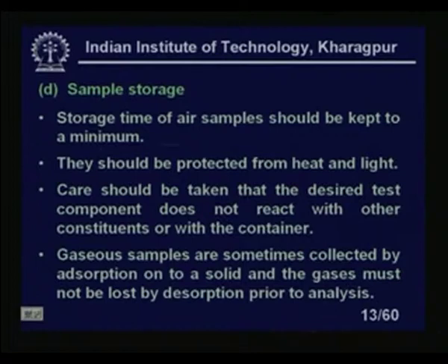Many samples are collected by adsorption, that means the gas will be on the solid material and it should not be released, or desorbed, prior to the analysis. Okay. Because if it is released before the analysis, obviously that particular gas will be lost, we cannot analyze it, and it will show that there is no such gas, but actually it was there, and by that time it is lost.